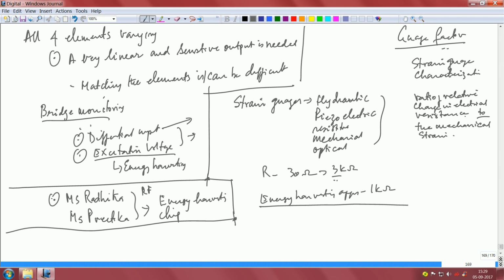Please look up Wikipedia, you will get to understand this very well. Gauge factor is something dealers will not tell you. Essentially when you go to a dealer to buy one strain gauge, they will not tell you the gauge factor of the strain gauge. So, you may actually have to perform an experiment and evaluate the gauge factor. You expect that the gauge factor is linearly dependent on the strain that you measure, whereas the strain is directly proportional to the bridge sense voltage. Okay. So, all this will have to be borne in mind.